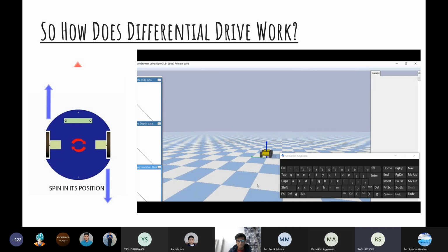Some cars use 4x4 transmission. Those are able to do differential drive. Differential drive is just where the axis of the motors is constant. They are rigid, and you rotate your motors either clockwise or anti-clockwise. When both motors are rotating clockwise, it moves forward. When both are rotating anti-clockwise, it moves backwards. And if you make a slight velocity difference between them, then your car starts to drift, and that drift is what allows it to turn. Okay.